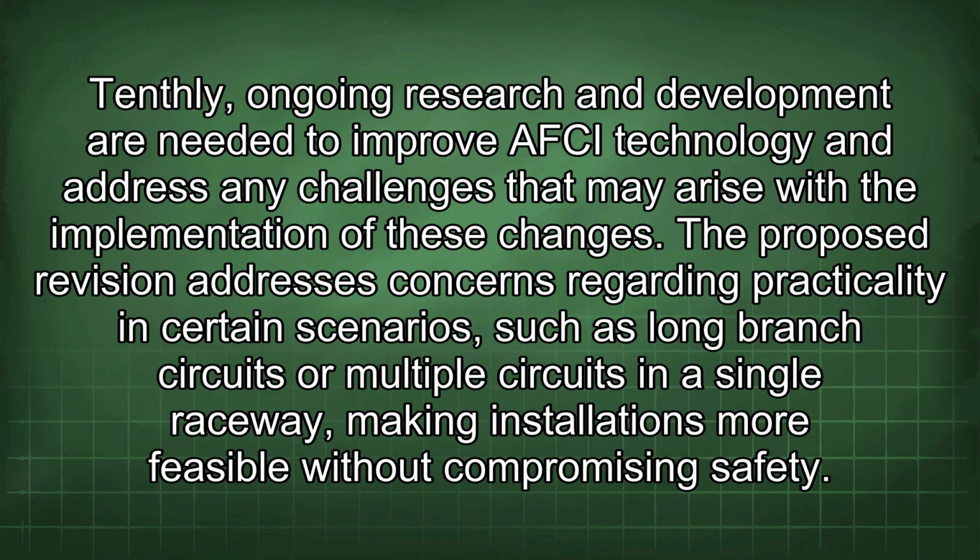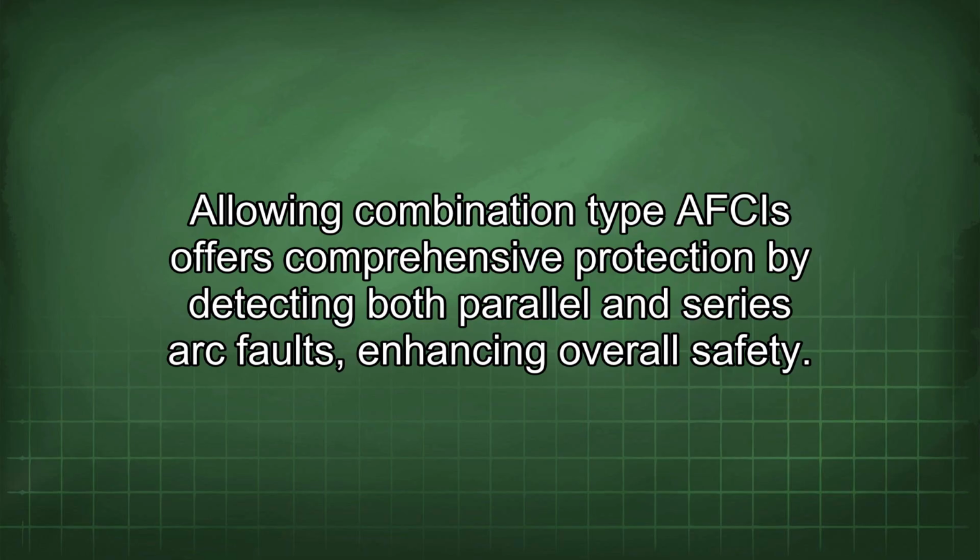Tenthly, ongoing research and development are needed to improve AFCI technology and address any challenges that may arise with the implementation of these changes. The proposed revision addresses concerns regarding practicality in certain scenarios, such as long branch circuits or multiple circuits in a single raceway, making installations more feasible without compromising safety. Allowing combination type AFCIs offers comprehensive protection by detecting both parallel and series arc faults, enhancing overall safety.